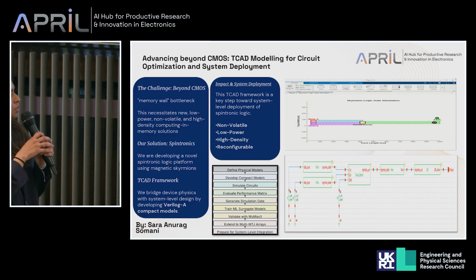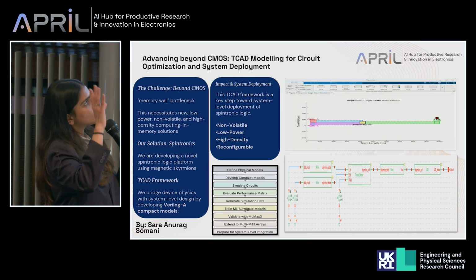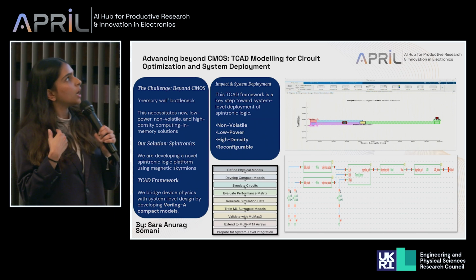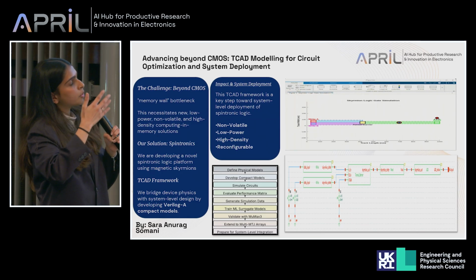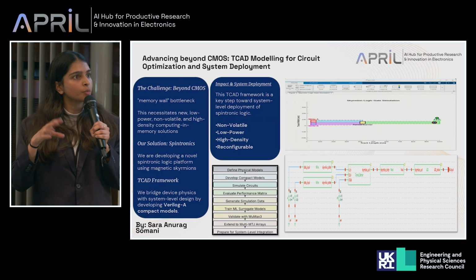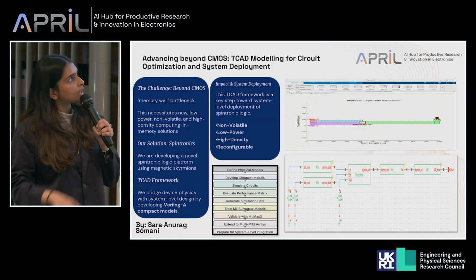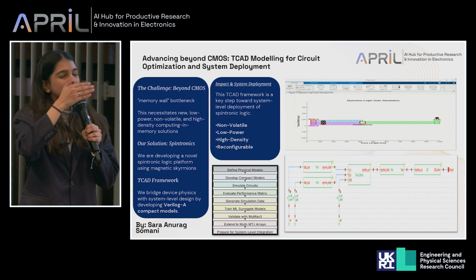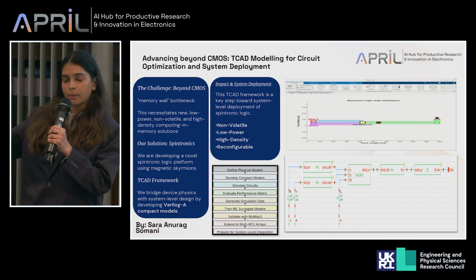When they move from one position to another, it does not require that much energy. If you take a quick look at the simulation, there are three different processes: the write, the tunnel barrier, and the read. Like Santosh mentioned, I'll explain how the Skyrmion gets generated. The Skyrmions get generated in the write process using an MTJ. Spin currents are injected into the MTJ, which nucleates the Skyrmion. The Skyrmions in this diagram represent the bit carriers. You can think of them as encoding information as they move along the way.